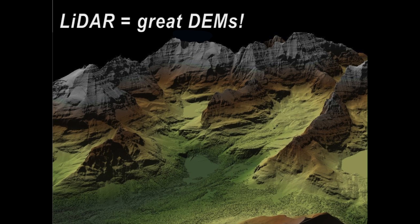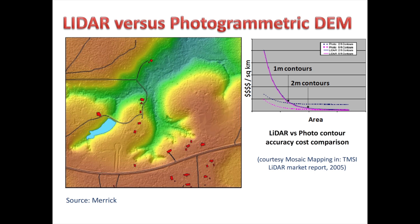For example, this is a digital elevation model from the Lake O'Hara watershed just near Lake Louise. This data set was captured in around about half an hour of airborne survey time, and it really didn't take too long to process it either. So when you compare that with photogrammetry, the efficiencies and the accuracies are quite obvious.